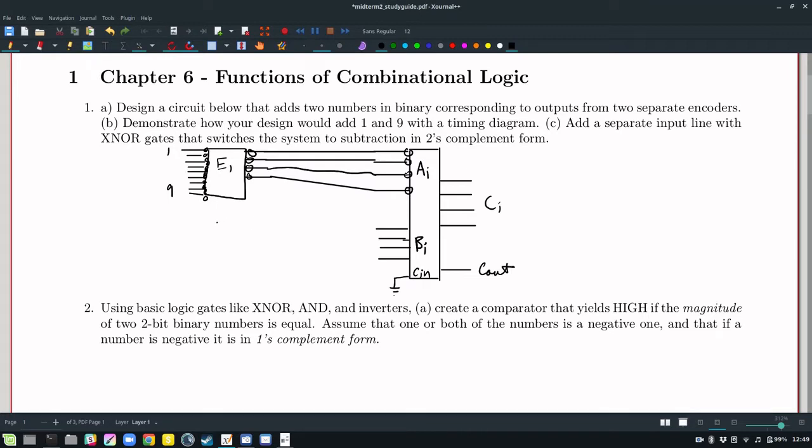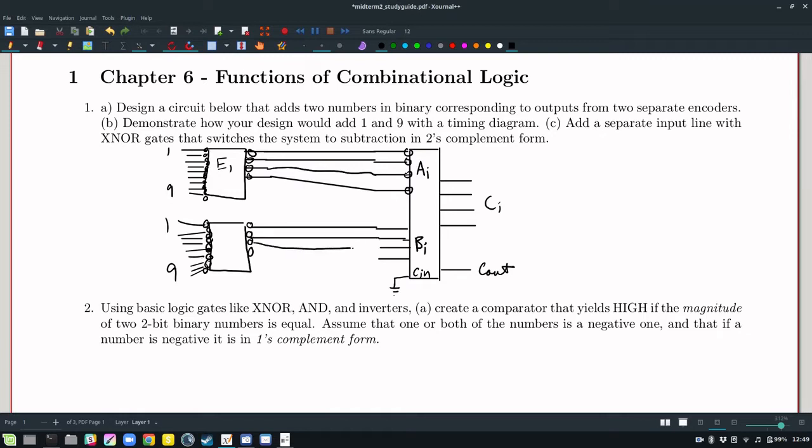Okay, now for the second encoder, with inverters on the outputs, and then 1, 2, 3, 4, 5, 6, 7, 8, 9. 1 through 9. We can just connect here like that. And then make these active low as well. And then we could press a key. So technically, we don't need a 0 key, because if it's active high, then these inverters will spit out 0. So 0 plus 0 is just automatically 0. But if we press something, then the adder, let's call this FA for full adder, will be forced to add whatever is spat out of either encoder. And that would accomplish the adding.